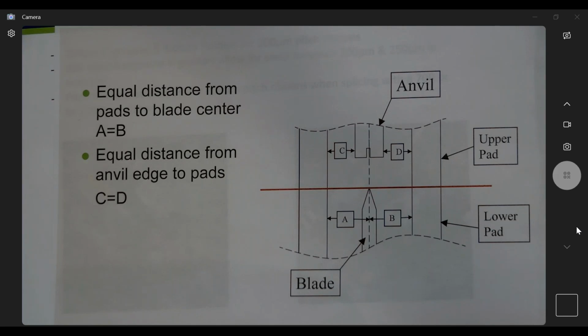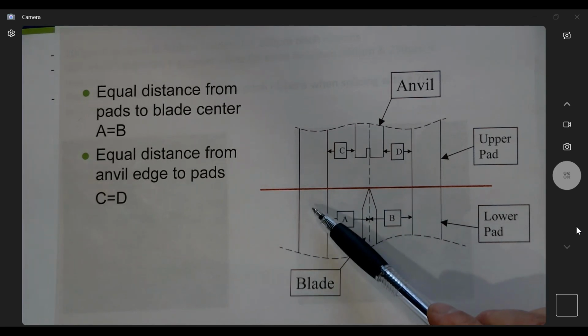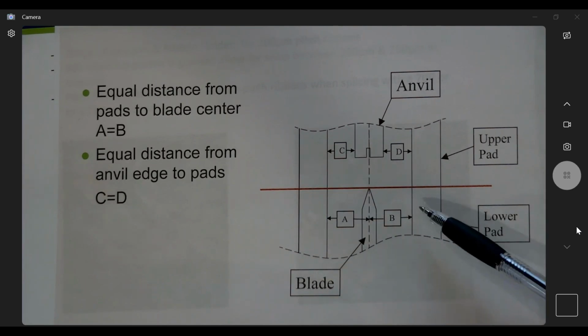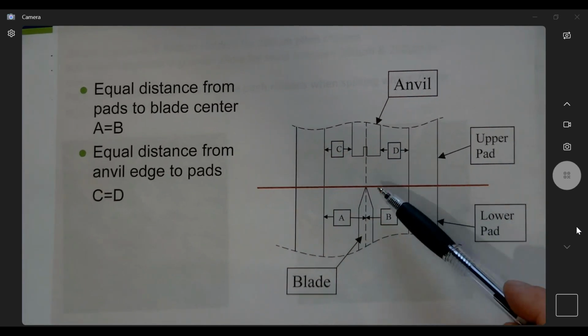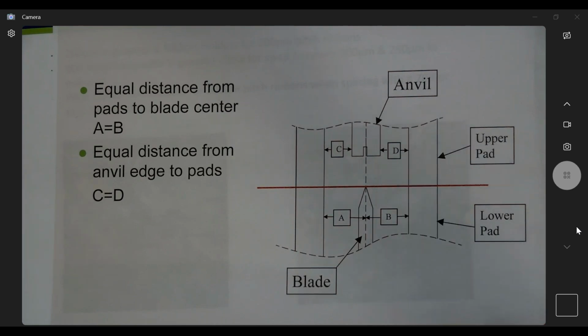I actually mentioned the splicer earlier, the V-grooves, the V-groove chip clamps. There's only 2 pieces inside a splicer that have contamination issues and cause actual offset problems. But with the cleaver, I can point those out real quickly. It's the left pad, upper, lower, the right pad, upper, lower, the blade itself, and this anvil. You want all this stuff to be in balance, even pressure, even tension. So as we go to cleave this fiber,